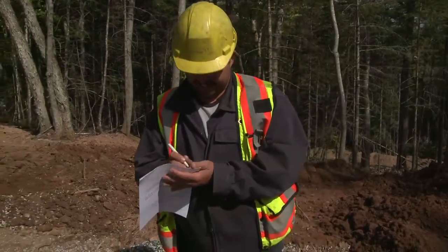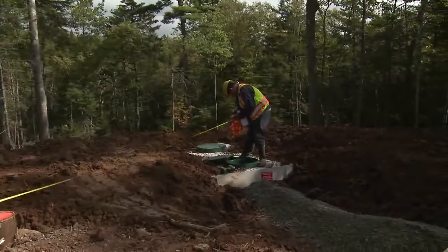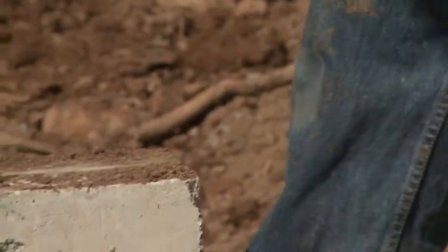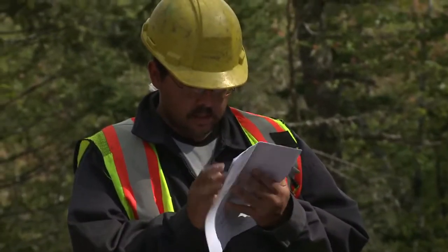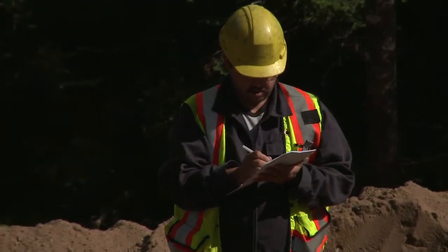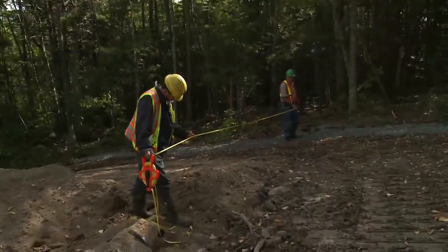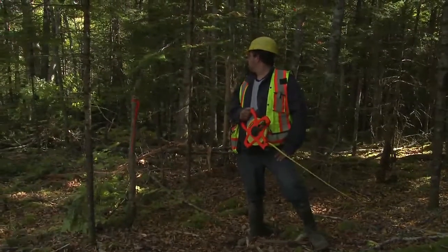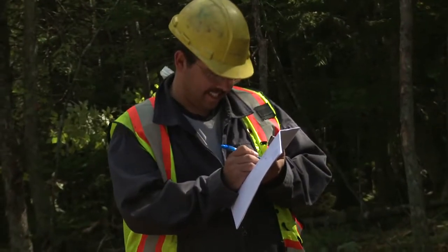The qualified person arrives for inspection. The QP ties in the location of the septic tank and disposal field to 2 fixed points. The separation distance is measured from the bed to the interceptor trench. Separation distances from the bed and the septic tank to the nearest lot boundary and downslope boundary are recorded. Other applicable separation distances required by the regulations are checked and recorded.